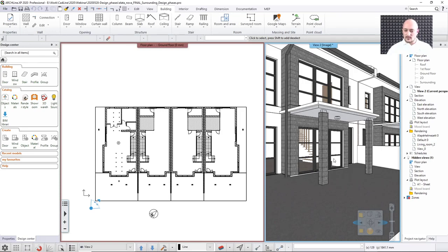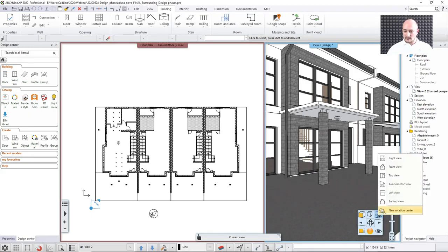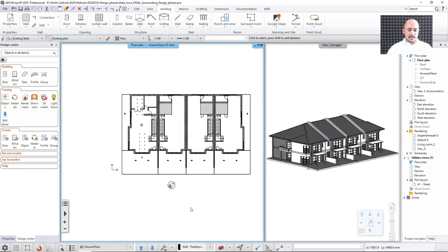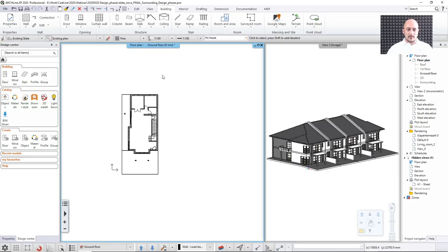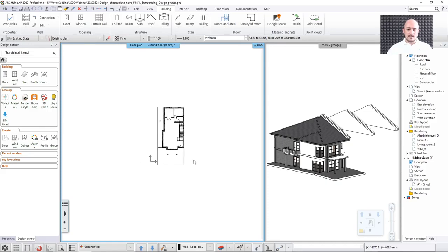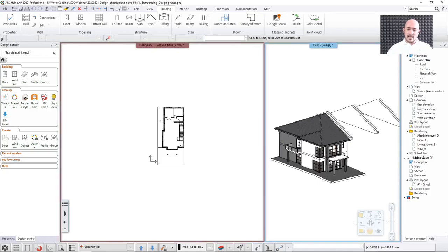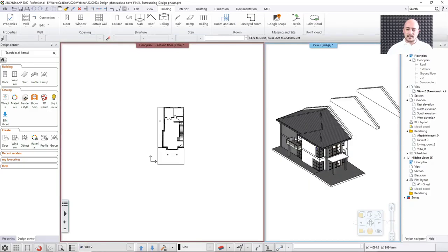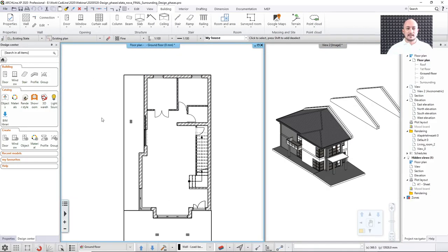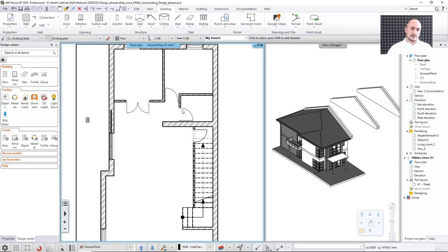Let me change this 3D so we will be able to follow the changes easily if I just use an axonometric view. And well, perhaps I can also filter this down to only the existing building, my part. Let me just rebuild the building in 3D. So now, I did not put these into the proper filter, but let me just skip those parts now. And as you can see, now the building here is represented in the existing plan status.